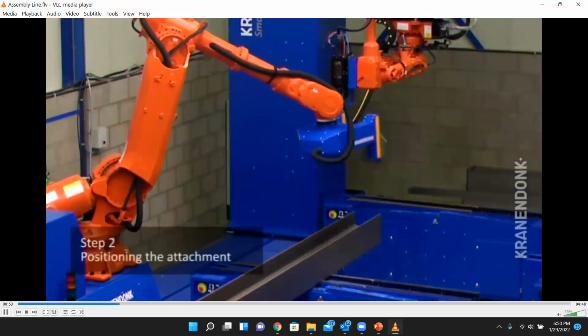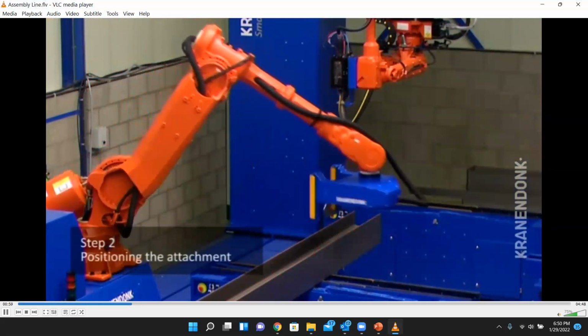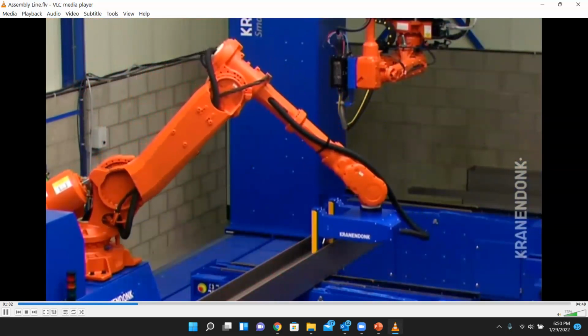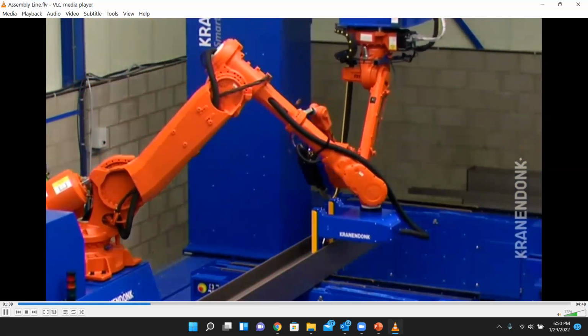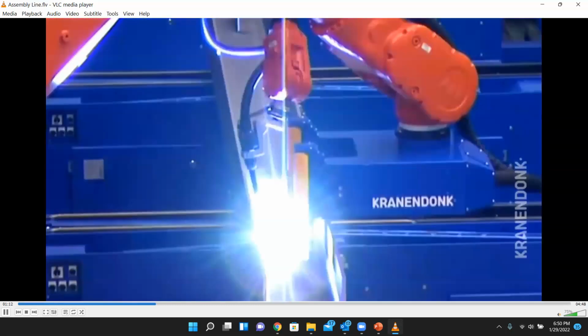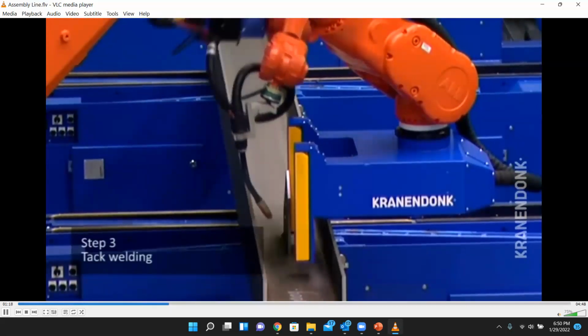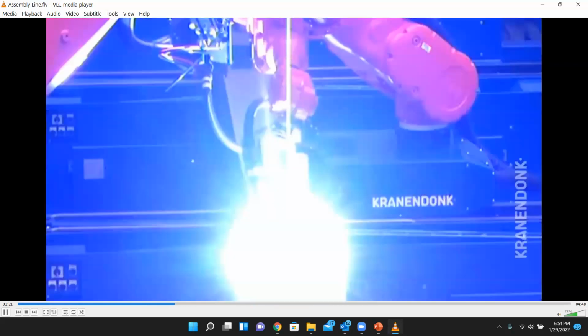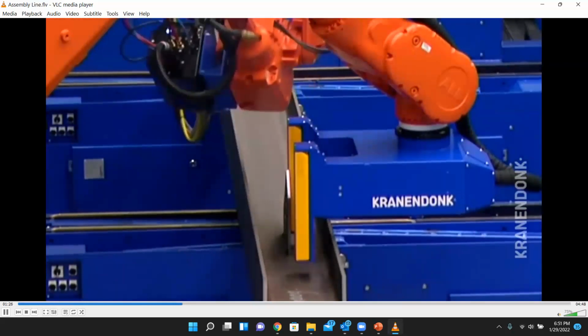These robots use vision technology and also infrared or maybe visible ranging sensors. So one robot keeps the object in place and the other one does the welding. It just puts the tag, the first tag, to hold the item in place. Now the first robot retreats, and the second robot, which is actually the welding robot, does the job, a complete weld, right?